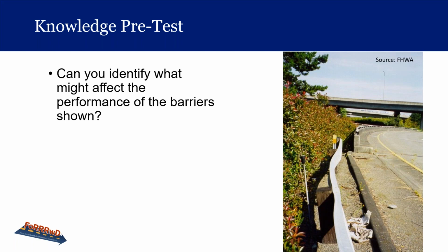Bunch of people putting curb, end treatment, resolution increase for sign legibility, posts and asphalt offset wrong, no end treatment, curb offset, bridge curb, some damage in existing barrier, transition between barrier types, offset from curb, no bridge terminal, damage to the existing guardrail, transition railing, need bridge terminal assembly. Those are all very good answers.